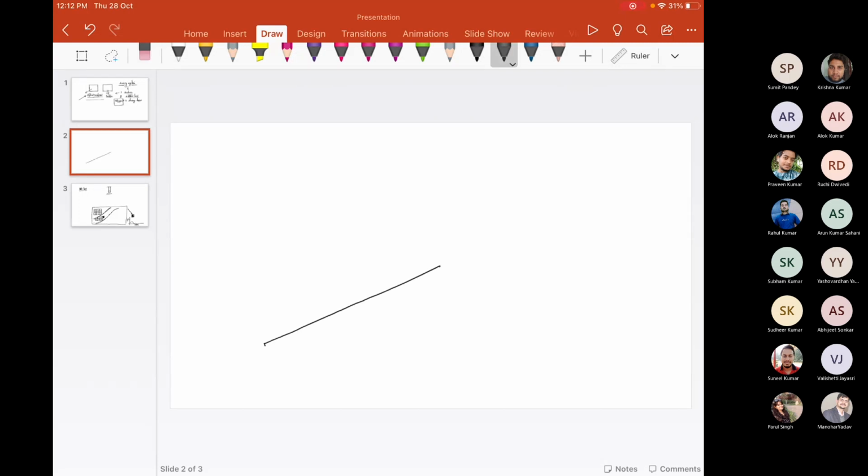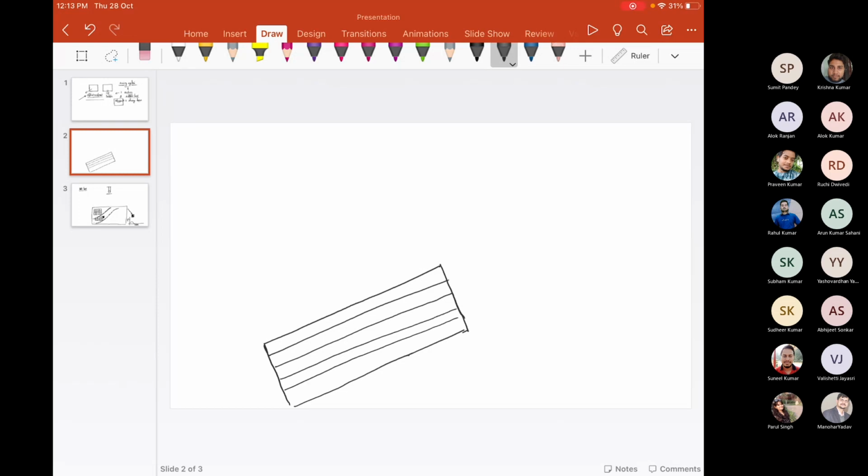For the discussion, I'm drawing a schematic where a rectangular area is taken and further gridded, where each grid represents a ground resolution cell. By capturing the energy from each individual GRC, the sensing system allocates a DN number.